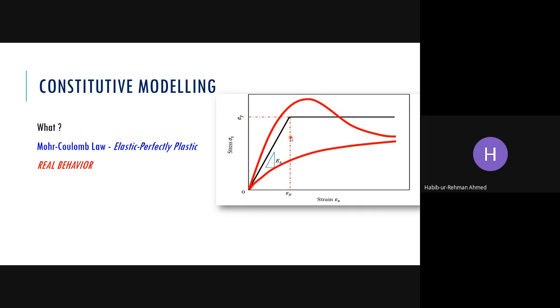And then they say, see, the results are same as the closed form solutions. So what is the use of finite element modeling? The problem is this, that we are incorporating a wrong behavior model in a highly sophisticated tool. So that will definitely give us more or less the same kind of result which we are getting from the closed form solutions. So that's why it's very important that we should have the realistic model so that we can